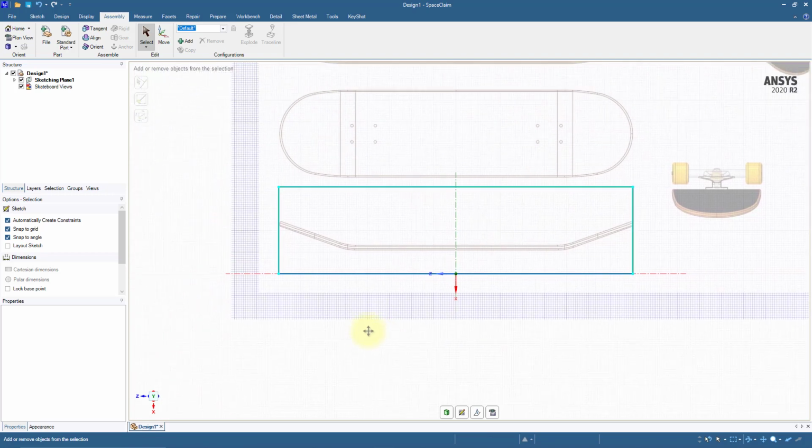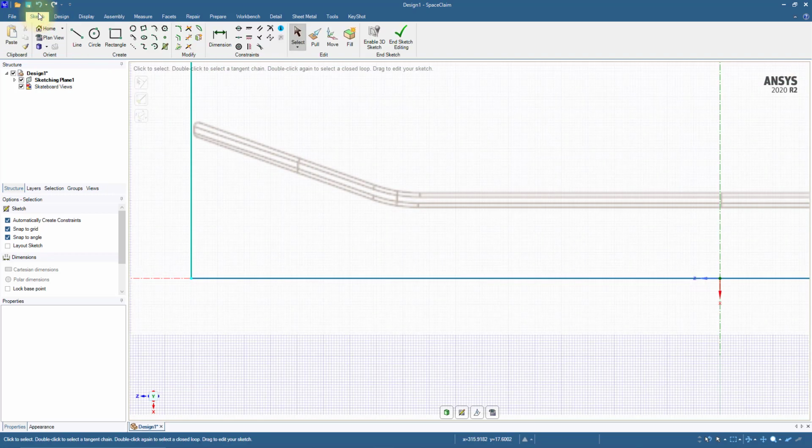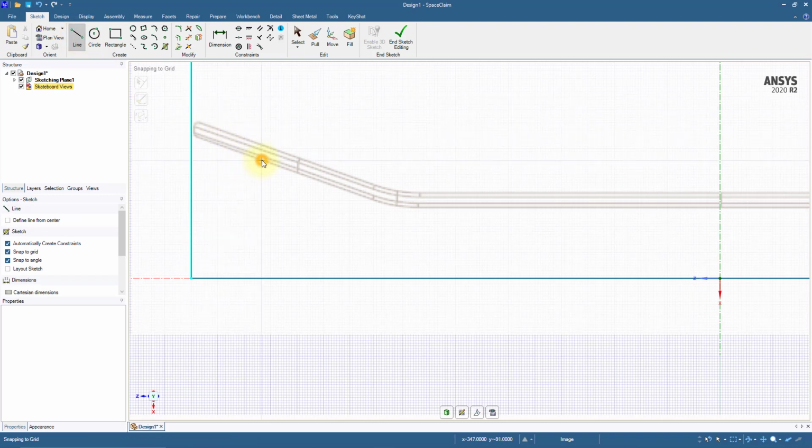Trace the image outline. Use the sketching tools in SpaceClaim to your advantage. Sketch 3 small lines along the bottom of the profile. Begin with one angled section. When creating the angled lines, keep an eye on the angle dimension. Use your best judgment to select what the angle should be. Here's a hint. It's probably not 159.3 degrees or 21.7 degrees. Don't worry about the intersections.